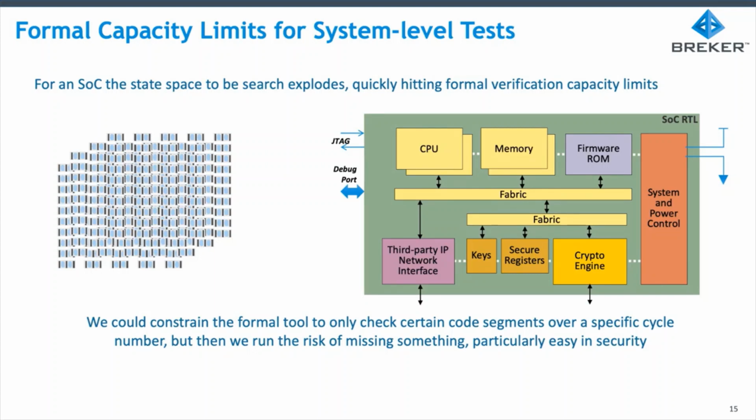However, the issue, of course, with formal verification is that it's capacity limited in that it has to store in its data structures the entire state space of a design. And this is very storage bounded as you start to look at larger subsystems and especially SOCs. So we can only run formal verification on relatively small or medium-sized blocks.